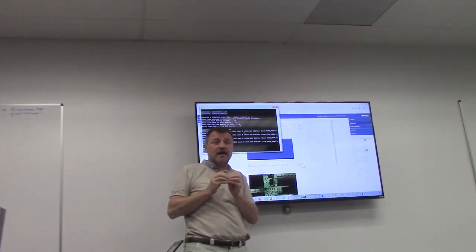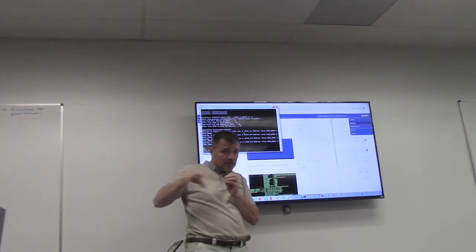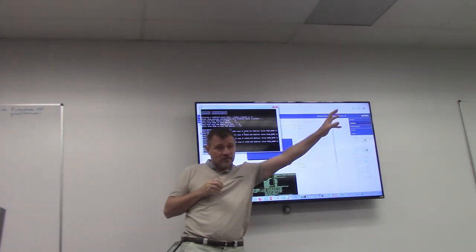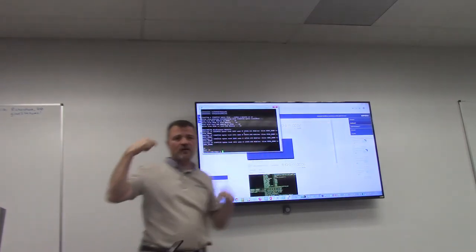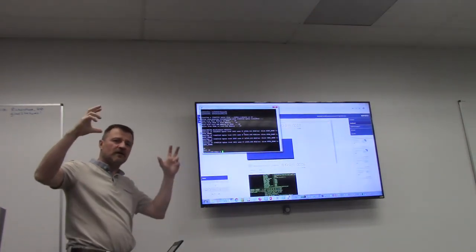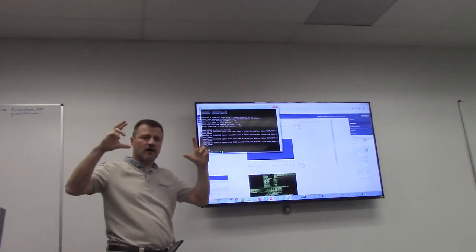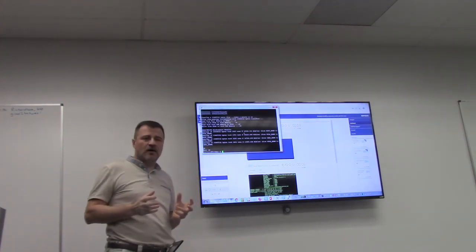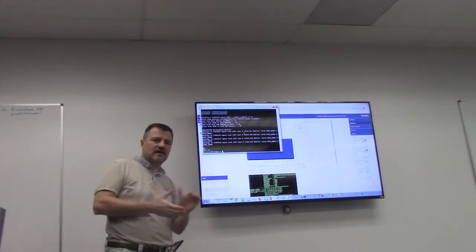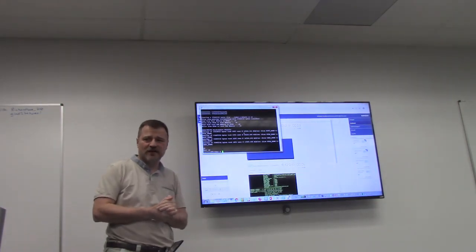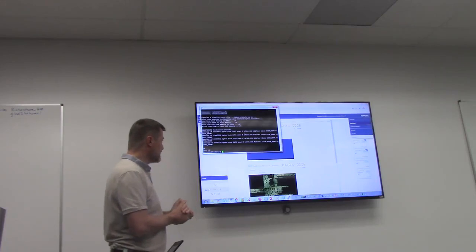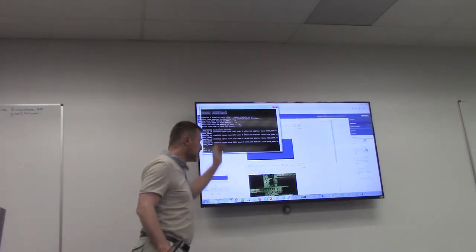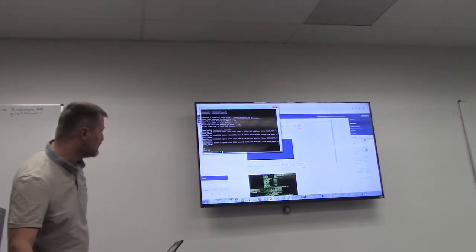But it's as fast to copy in the local DDR on the card as it is to access the host memory. If you remember the card we saw at the beginning, Alpha Data is making a card with OpenCAPI, and they don't put DDR on the card because they estimate that the access to the host memory is fast enough to provide good access. So it's an example that you can run on your card to make sure that you have the right performances.